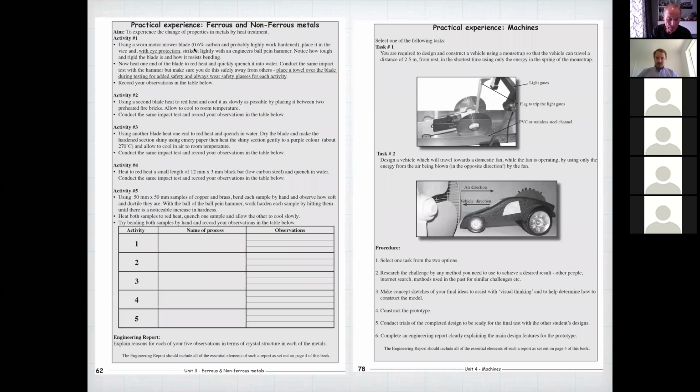And then I'd put both of them in the vise, show them that the 0.1% isn't affected by heating and cooling, and the mower blade, put that in the vise and you just tap it with the hammer and it would fracture very easily. And I'd just say, you could just imagine if a mower blade in this condition was put in a mower, it would just fail with the first rock it hit.